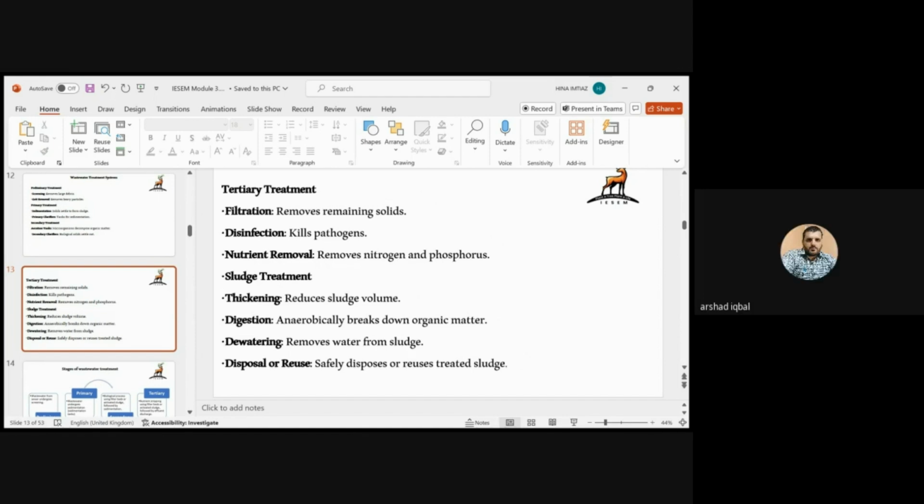Yes, ma'am. Yeah, so you know that in the final step the product also undergoes screening to ensure that it is free from any chemical or potentially harmful compounds. Various cities around the world rely on treated wastewater to boost the supply of clean and safe water for drinking. Keeping the final product free from chemicals is one of the topmost considerations before supplying any clean water to the consumer. So if the objective is to reuse that water for drinking purposes, you have to be very conscious about the tertiary treatment.